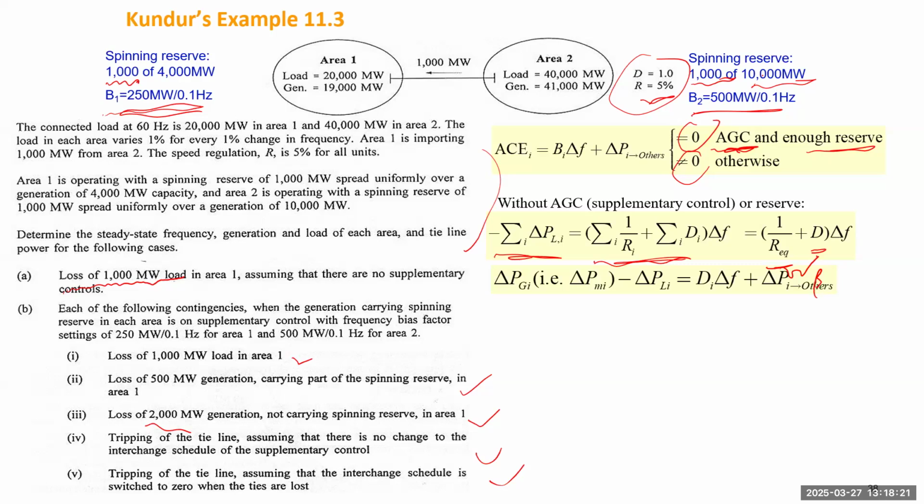So next one will be still based on the power balance. In this example, each generation of generator is called PG, which is basically just mechanical power. Left hand side is total generation change minus total load change. The right hand side will be the load change on the frequency dependent load and also tie line flow. This is based on the power balance.